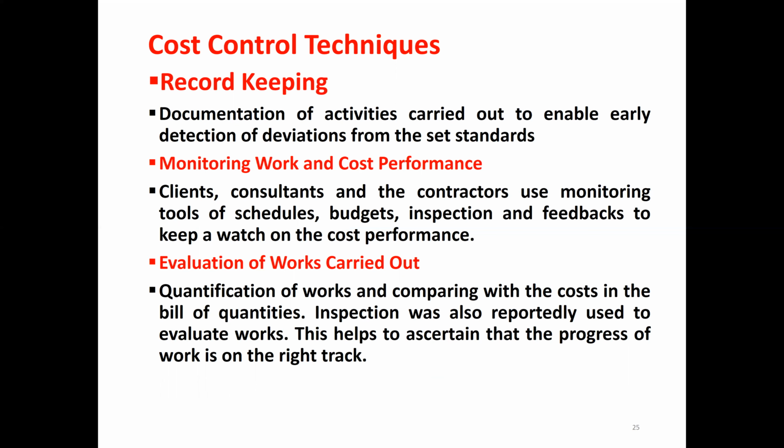The last technique we can use for cost control is evaluation of work carried out. Quantification of works and comparing with the cost in the bill of quantities. Inspection was also reportedly used to evaluate work. This helped to ascertain that the progress of work is on the right track.